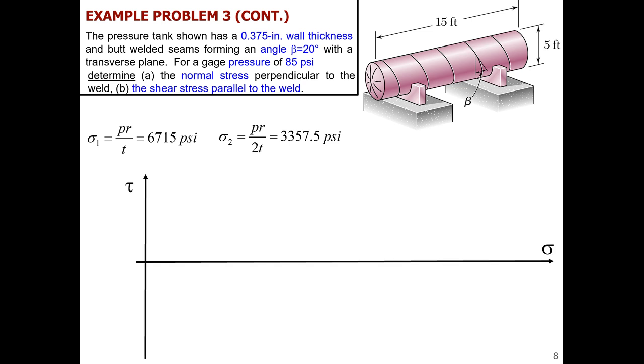Okay, so again, we were going to use our Mohr circle. Let's build that. It's not a problem because we know our principal stresses, sigma 1 and sigma 2. Immediately we can calculate the central point, the average stress here, sigma 1 plus sigma 2 divided by 2. That will be the center of that Mohr circle. And we also can put the radius here, which will be the difference.